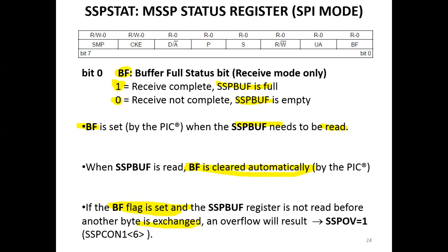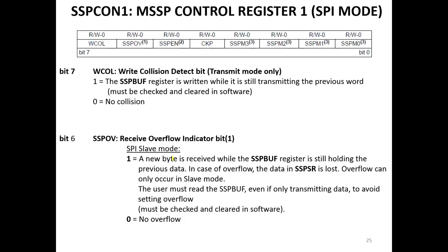And there is a flag to detect this overflow, which is the SSPOV, SSP overflow. So if the SSPOV from the SSP control register is 1, that means there is an overflow. So this is the SSPOV.